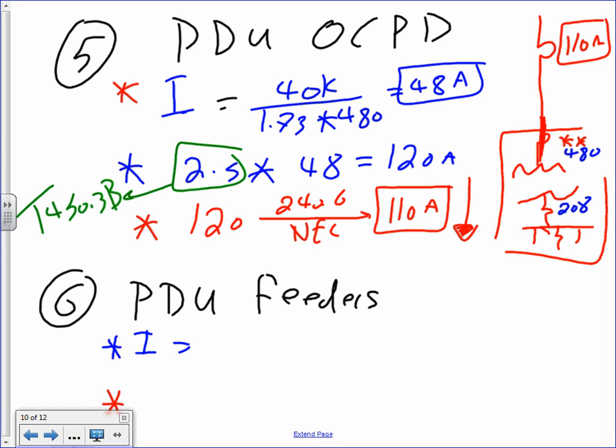You take two circuits, a plug, there will be a 208 plug, just 208 with a ground, and you wire a plug, and you plug the server into the 208. If it's 120, no problem, a neutral and a ground: ungrounded conductor, grounded conductor, and an equipment grounding conductor, and you plug in with the 120. Okay, the last thing we're going to size, my friends, the last thing,